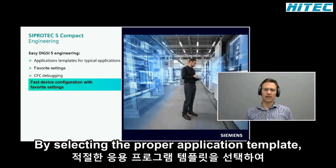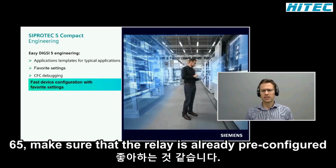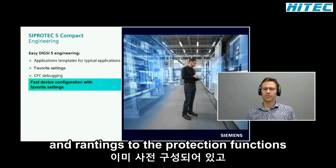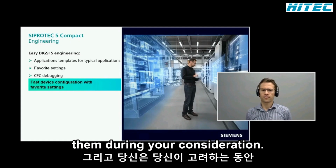By selecting the proper application template, for example, a directional overcurrent relay in a solidly grounded system, DIGSI5 makes sure that the relay is already pre-configured with the necessary functions and routings. All the necessary preparations, like connecting current and voltage values to the protection functions, are already predefined, and you do not need to take care or worry about them during your configuration.